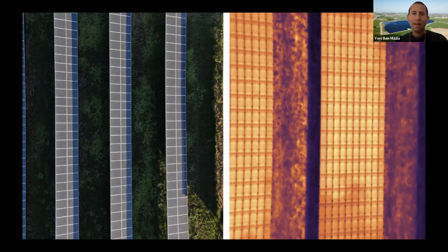Mm-hmm. Yeah, if I can add to the right picture, for the audience who might not come from the PV industry directly, or who are not pilots or O&Ms: what you see in that picture is that some of the modules are very bright yellow and some of them are darker. That means the brighter yellow modules are partially shaded, probably by the clouds. That means they're producing less and sort of becoming a consumer. And this is why they're hotter than the producing modules, which you can see on the, let's say, right bottom side of the long table.